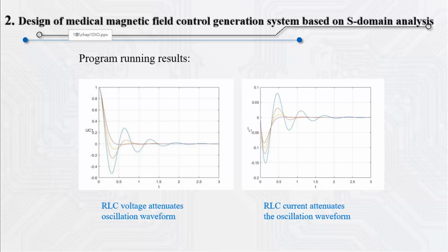During decay oscillation, coils and capacitors exchange energy periodically. Resistance is consuming energy all the time. This process principle can be used for pulsed magnetic field generators, and can also be used for reuse when the magnetic field generator is powered off. When the magnetic field generator is powered off, energy is stored in capacitors, in order to achieve the goal of energy-saving reuse.